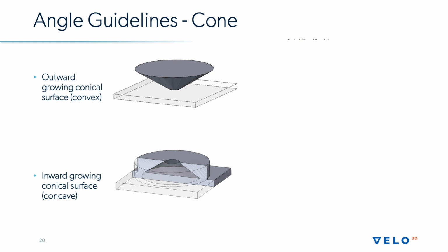And what's happening in this part on a high level on this type of geometry is you have two basic forces that are working together that may lead to breakdowns. One is sort of global residual stress in the bulk of this part that's shrinking each layer, kind of like the very simple example I showed in the beginning, and pulling the geometry inward towards the center of the local mass. And the other one is the skin process, the melt pool of the skin process, which basically forms a ring around this geometry. And when it melts, it does something similar, but it's in a different orientation. It contracts and wants to pull inward.